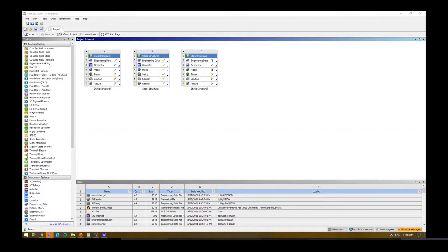So hopefully before starting your actual project, you'll be able to map out on paper, what material properties do you have? What are your joints, contacts, and connections? What are your boundary conditions? What have you been given, and do you need to make some changes to them? And how is your component supported as well? If you've got multiple bodies, how do these bodies interact? And what are you actually interested in, right? You look for your force, displacement, stresses and strains. Is it plastic? What material properties are appropriate?